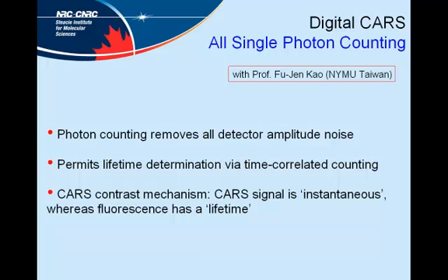In our setup, particularly because we are doing live cell imaging, what we found is these hepatocytes are very sensitive to the laser light. We really had to turn the laser light down before we convinced ourselves that the laser was not modifying the experiment. We quickly realized that our photons are basically coming one at a time. Our anti-Stokes photons are coming at less than 1 per laser pulse. And that was perfectly fine for imaging because the laser is at 80 megahertz, and that was plenty of signal for us. But if you realize that the photons are coming one at a time, then you're making a great mistake using analog electronics to detect these things, because you're just adding all the analog noise into your measurement.